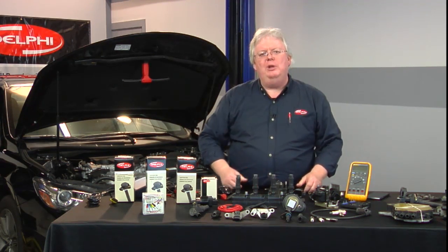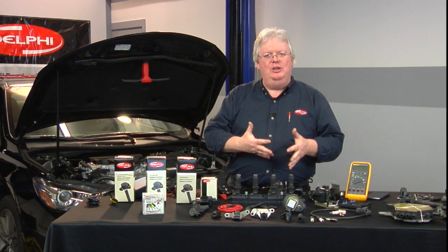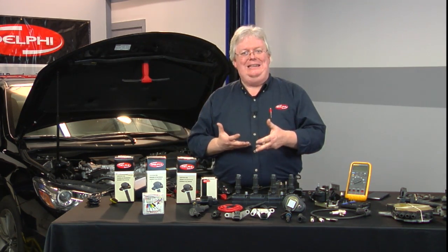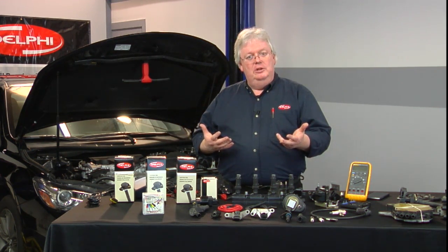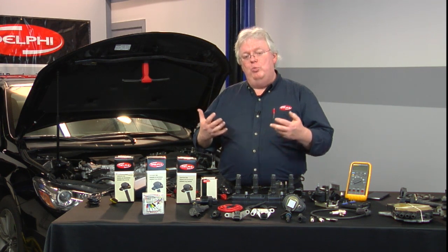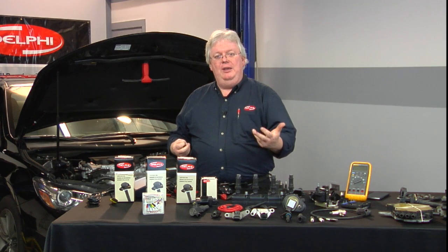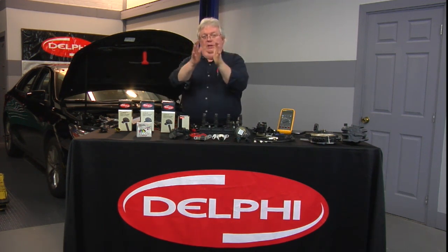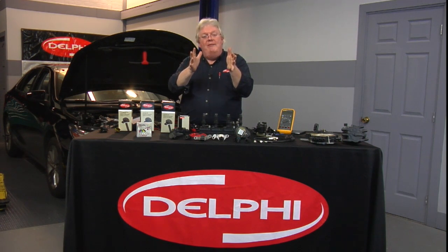The only way you can really bring the beast out, so to speak, of carbon tracking in a coil is to do either, in the factory, load testing, or MacGyver it on the car, which means a dyno under a load, looking at a scope, or on the road with another driver while you're operating your scope and you're watching the same thing under load. You're looking for a breakdown. What you'll see is normal kV demand for your firing line and a normal line left or right as to how long it takes and so forth, how much spark burn time we have. That'll all decay.